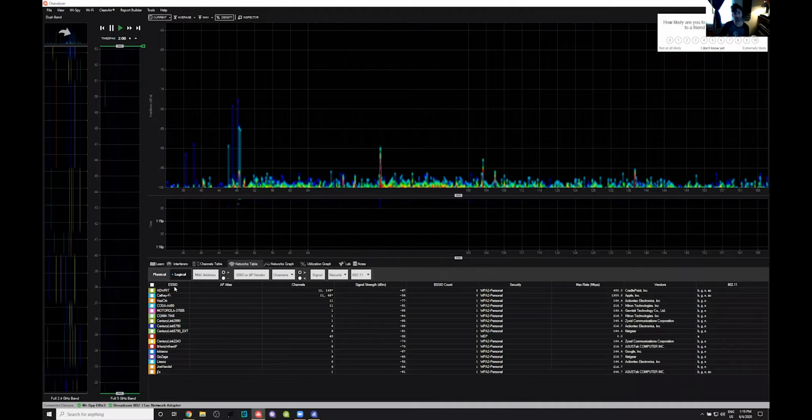to my laptop, because I don't really trust Wi-Fi, especially when I'm going to introduce this signal here. So I'm going to introduce some interference, and you're going to see how Channelizer works and how it starts to notify you of this interference. This is a significant interferer here that, we'll pretend, is intermittent. But right off the bat in this waterfall over here on the left-hand side, you can see some activity starting to form. And the reason why I'm Etherneted in, by the way, is because when I've introduced this source of interference, it's actually kicked me off the network and kicked me off the demo or the webinar.